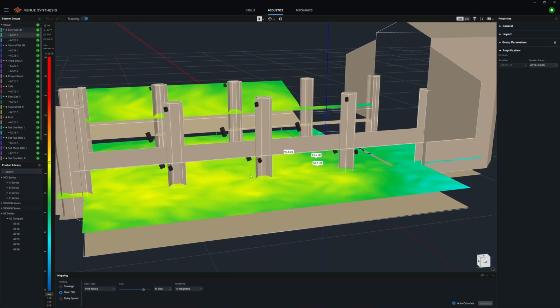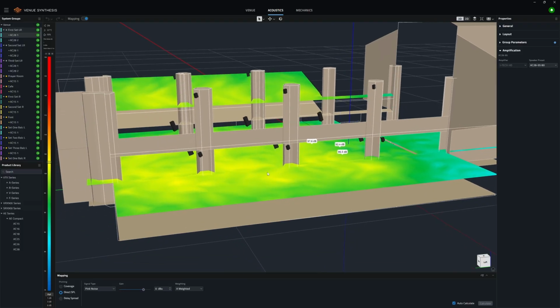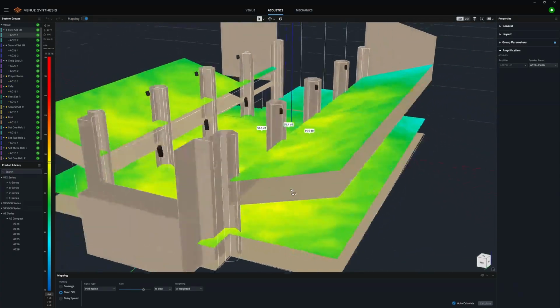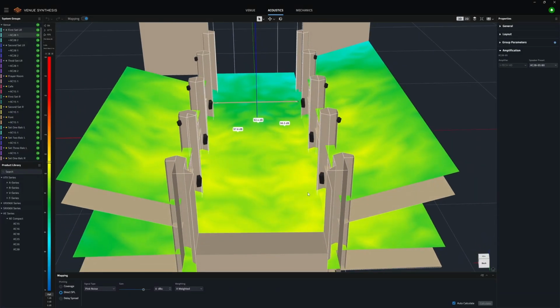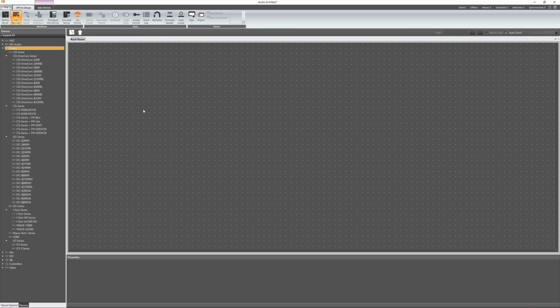And then for the other side, I think for the last 3 sets, so this distributed area, the bottom and the 2 balconies, because these small little 5-inch speakers are 16 ohms, I will put them all together, daisy chained, so then they are 5.33 ohms, if I remember correctly, which will then mean less amplifiers total, which is total saving cost. So then it's looking at the power.